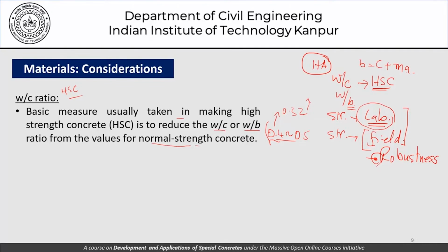I'll encourage you to read literature and find out from that point of view what is the kind of strength that has been reported in literature for concrete in laboratory studies, and what is the kind of strength which has been reported as far as field is concerned, as far as actual applications are concerned. There are differences when it comes to field applications or actual project applications of high strength concrete because of the nature of production, the curing and so on, and that prevents us from achieving the kind of results that we achieve in the lab in the field conditions.